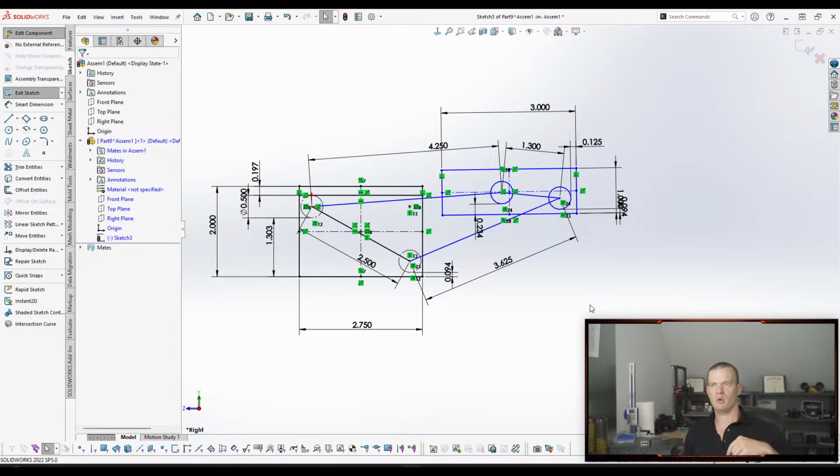There's bottom-up, which is where you, let's do a FaceTime real quick. So there's two different methodologies when it comes to parametric modeling. There's bottom-up, where say I'm drawing a block with a hole and then a pin that goes through it. Bottom-up is where I model the block and define the dimension, and then I model the pin and define the diameter dimension, and the two diameter dimensions I defined have to match. So top-down is where you create some type of relationship, or variable, defining what that diameter is, and then you push it to the two parts.